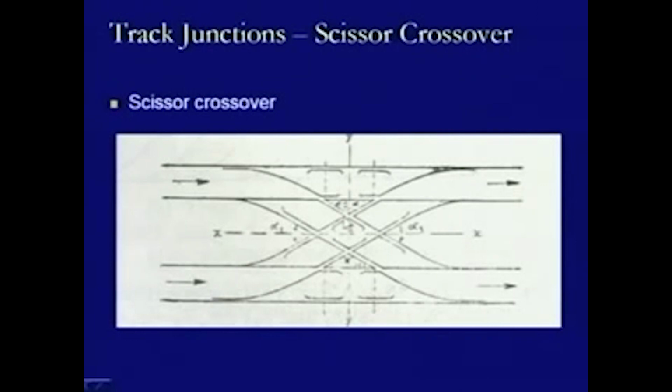In the case of the obtuse angle crossing also, we found one crossing in this location and one at this location. So, we have a wing rail here on this side, as on this side, but the other wing rail becomes a part of the diamond crossing. So, we have a wing rail pair provided inside like this here as well as this way here. And we have the check rails being provided.